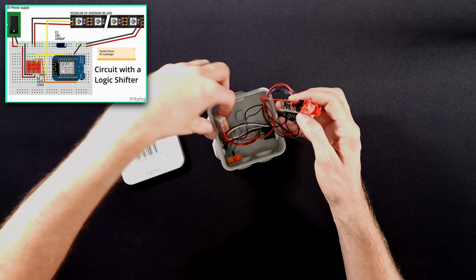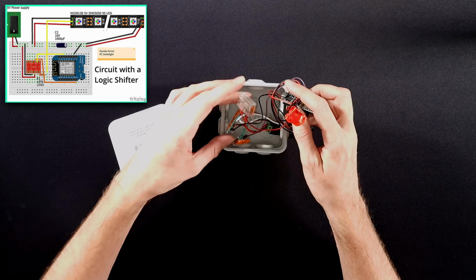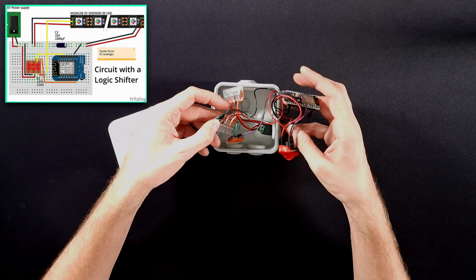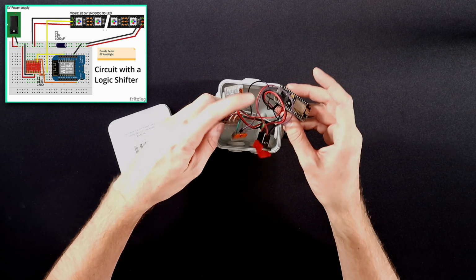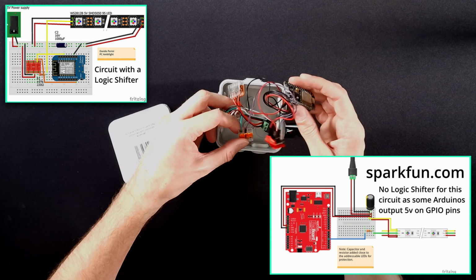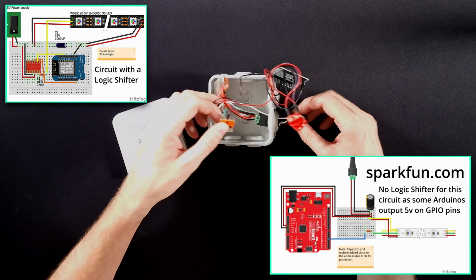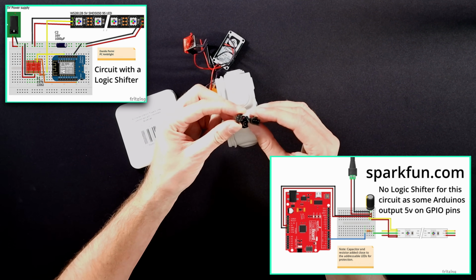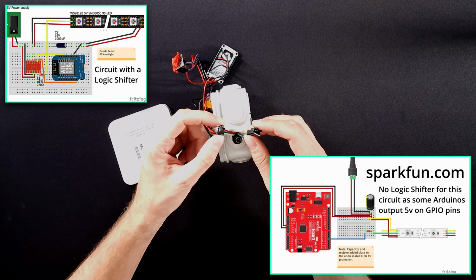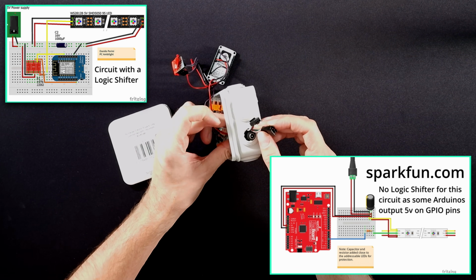And then if we look at the Wago connectors here, you can see I've got all the positives joined together here with one of them. And then I've got all the negatives joined together here. So we connect the negative from the power coming in to the microcontroller and also to both of the grounds on here. And then here this simply connects the GPIO out pin from the logic level shifter to this, which then goes to the output, which is one of these. And then the other one is used for power injection. So one of them goes to one end of the strip and the other one goes to the other end of the strip to give power at the other end. And this just ensures a more consistent lighting.